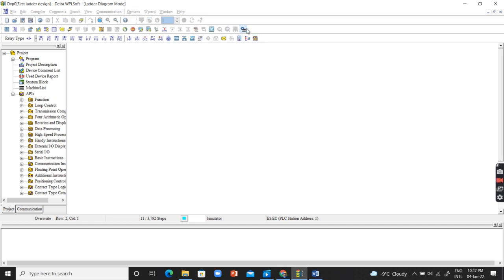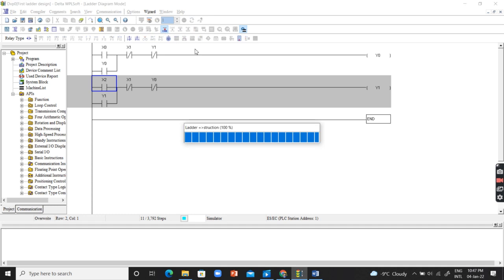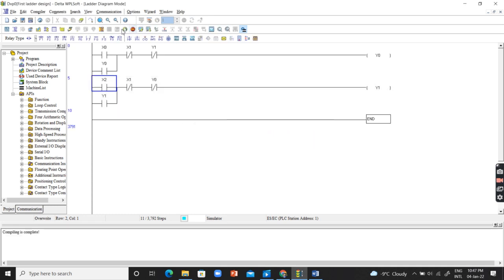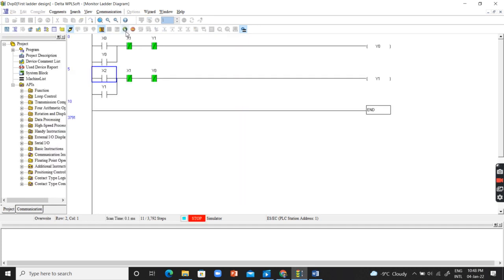We'll go to the simulation mode. We'll just compile the code, and we will try to analyze how it would behave, right? I'll turn the PLC on. Over here, the first thing before we go ahead is that this X1 is the same over here. And this X1 right now represents the power supply to the circuit. If the power supply is detected, then only it allows the circuit to work. I'll show you with the motor.